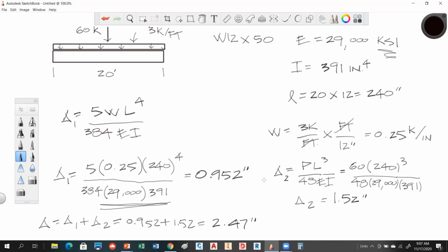So let's look at how that works with an allowable situation. If this beam was a roof member right now that was supporting a plastered ceiling, and it's a dead load plus a live load, let's say, does this meet the allowable? Well, the allowable deflection in that case, if you notice on that chart on table 12.2, if this is a plastered ceiling, let's say it's a floor member, but it's the same.